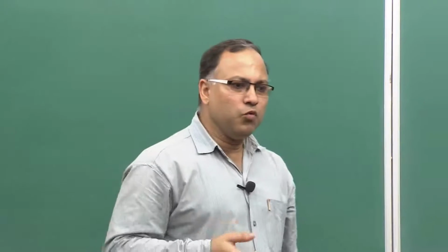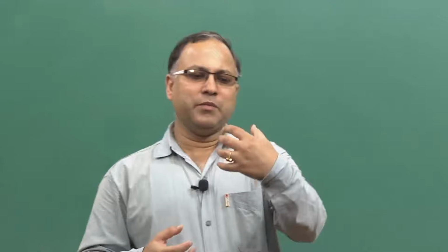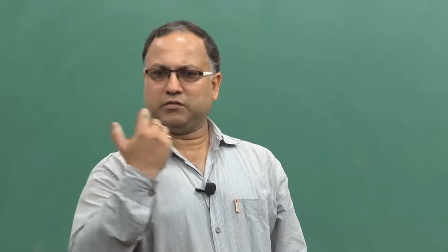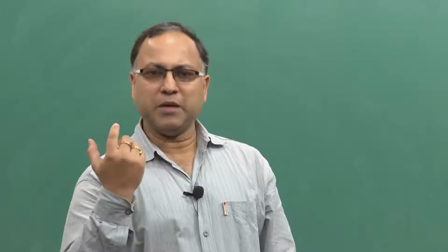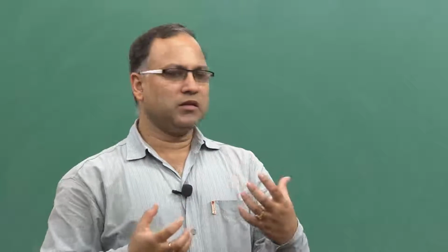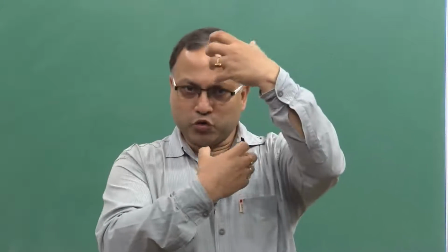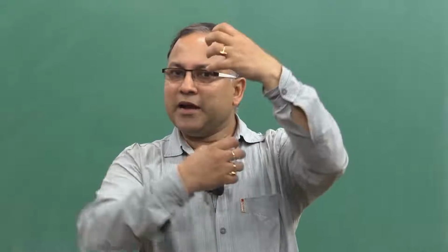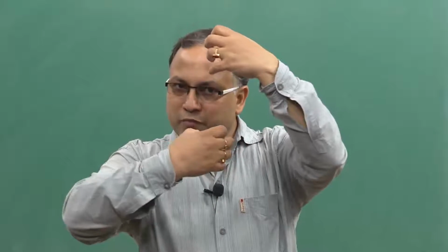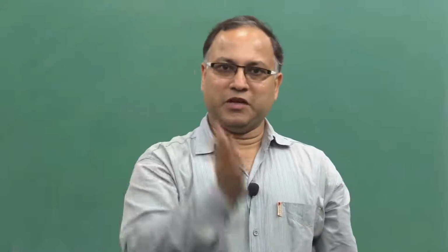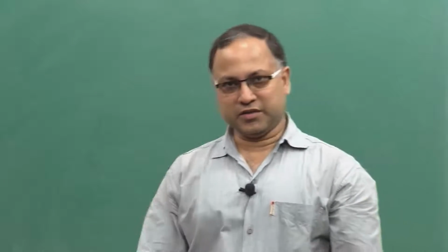Similar kind of thing you might get if you make a very thin cylindrical, slender member with paper, and you give pure twisting moment. The paper will be folded or warping along a particular plane on which the maximum shear stress is acting.